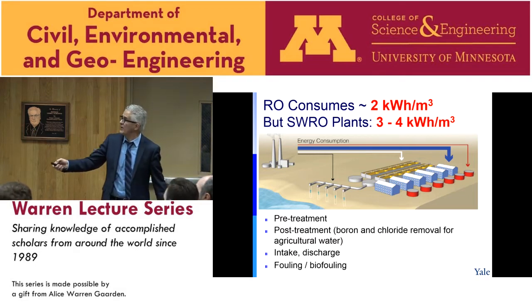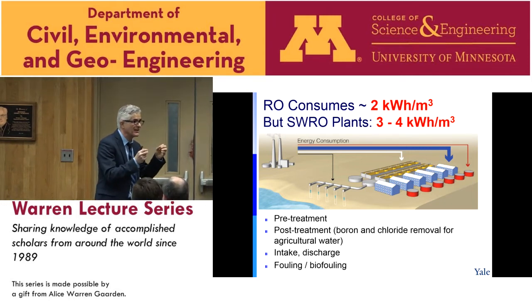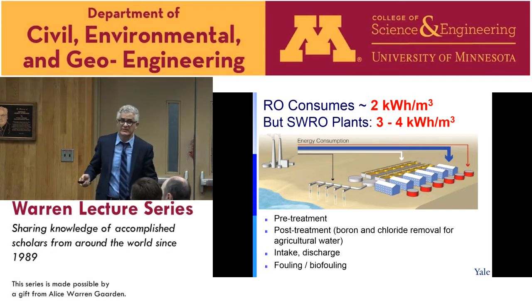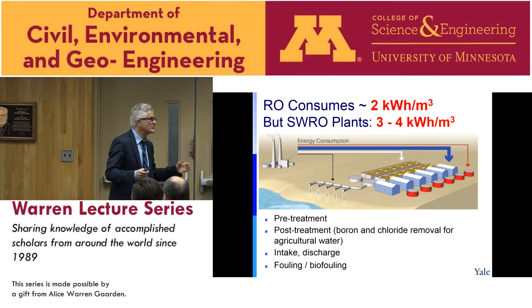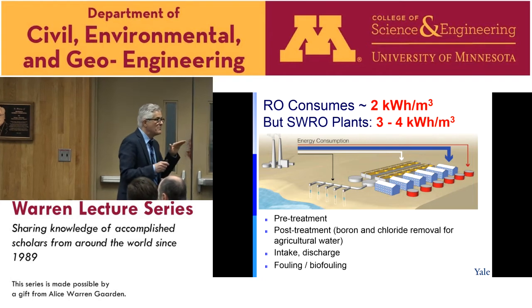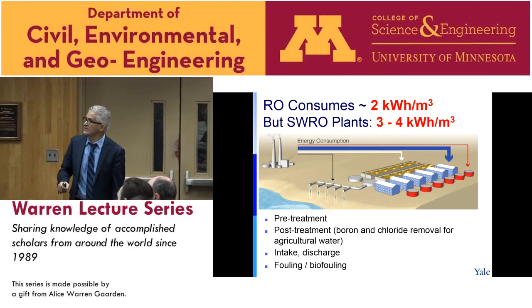And what they do in Israel, because the reverse osmosis stage does not remove boron effectively. Boron is uncharged, low molecular weight, and anything that is neutral can go through reverse osmosis relatively easily. So in Israel, they have another 3 stages of reverse osmosis just to remove the boron. So eventually, when they get the wastewater, it will not have high levels of boron, because many crops in agriculture are more sensitive to boron than humans. Indeed, the regulations for many crops have lower tolerance levels than for human health. Okay, so this is question number 1.